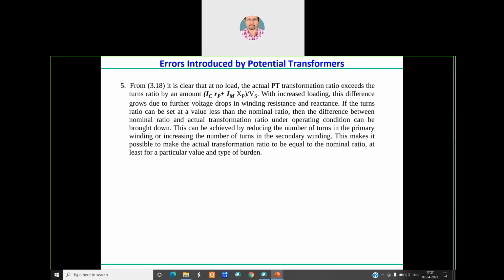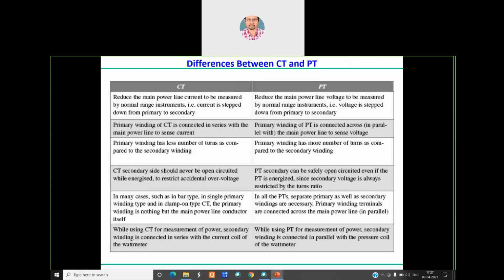You can say if you at all ignore from the secondary side. But if you are dealing with the current transformer and you try to ignore it, you may have to compromise with the life of the human personnel involved on the secondary side. Very dangerous.